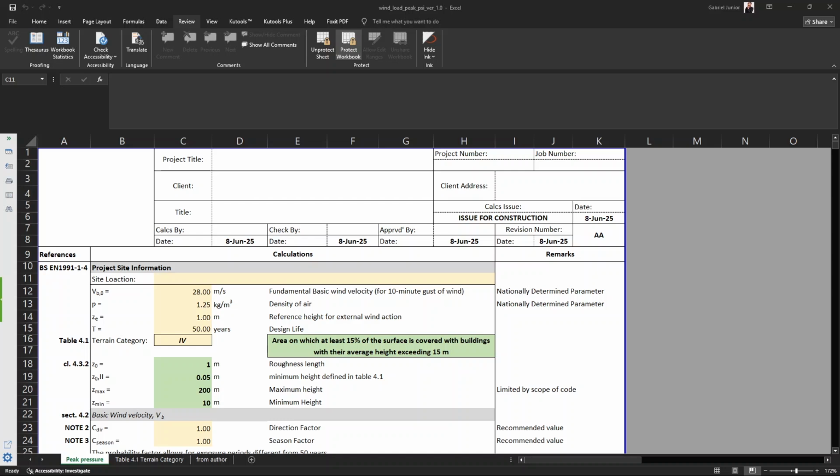Of course, from meteorological data, you can find different values based on different wind durations. You can have 3 seconds, 1 minute, 1 hour. So it's upon you to make sure that you're modeling with the right duration of wind. There are various ways you can convert this. Just check through the literature and you figure out how to do it.